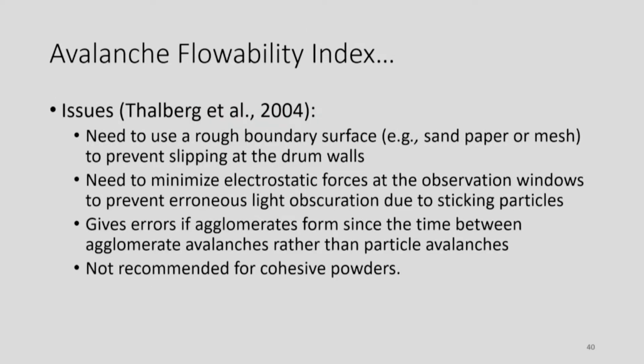As I said, friction we have to be careful of. If you are using a rotating drum or avalanche tester, the friction should be high so that the powder is not sticking to the walls. For example, if you are using a plexiglass drum, then the powder might stick to the wall rather than flowing or moving. If the particle sizes are small, there will be a high chance of electrostatic forces. In general, for anything less than 500 micron, there will be some amount of electrostatic forces. And when powders are moving, there will be high formation of electrostatic forces between the particles, right?